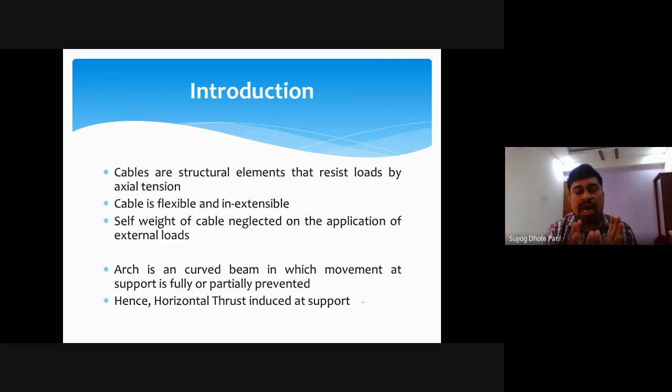If we think about both arches and cables, there are only two possibilities: one member will be under compression and one member will be under tension. A cable is supported at two ends with a sag in it, so there will not be any compression. All the vertical or gravity forces will be carried with the help of axial tension in it.